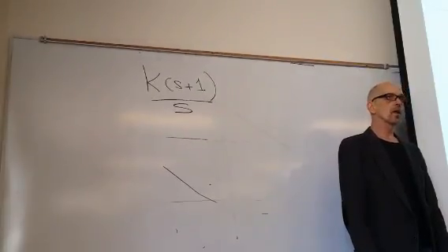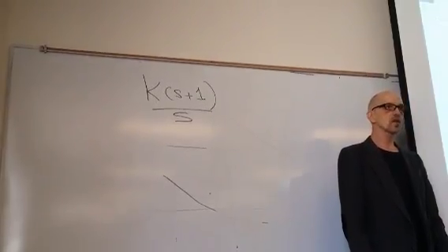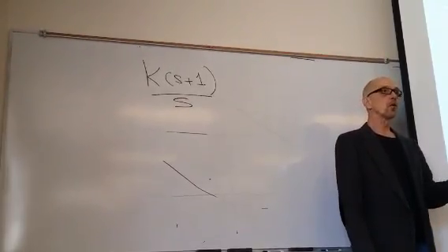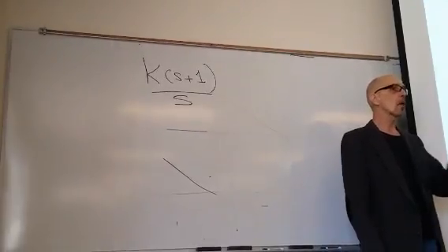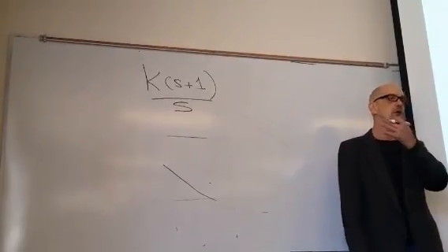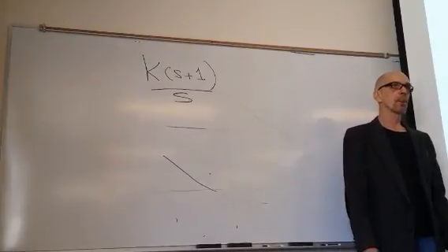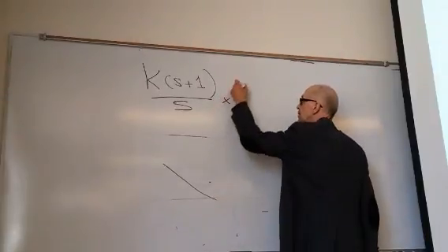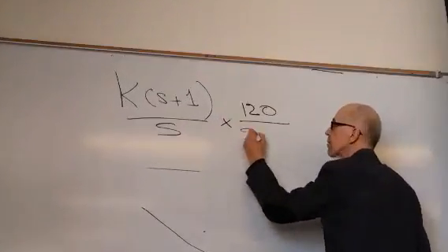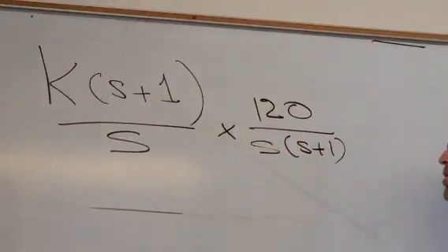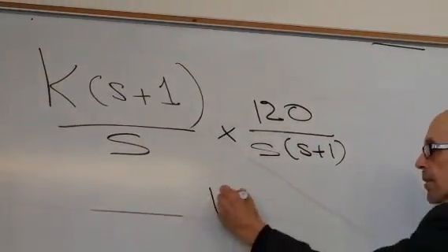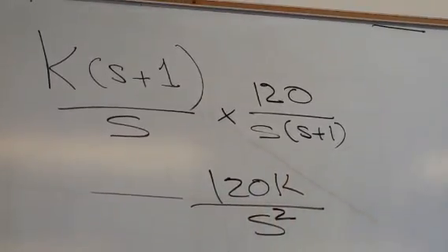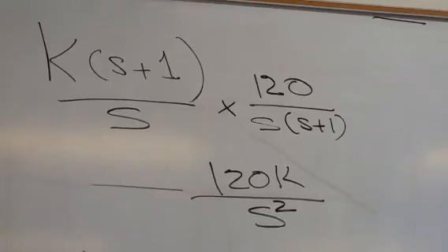The only way, if you do it correctly, that you can get 0 steady state error for a ramp is if the closed loop system is type 2, which means finite non-zero error for a parabola. So let's assume that you put a controller like this in here. So there's your controller. What's your plant? What's your open loop? Correct? Got it?